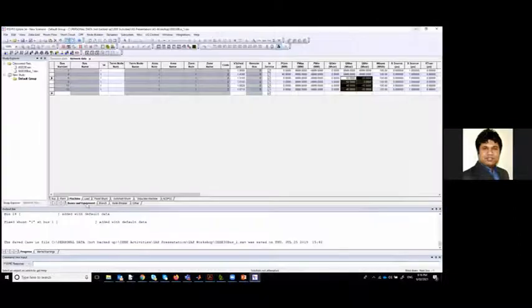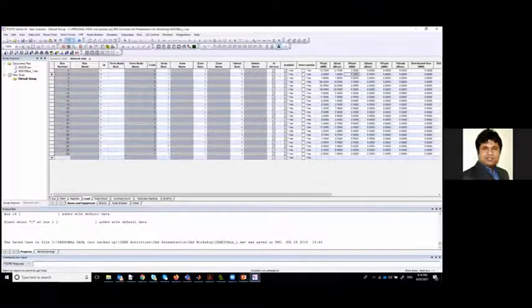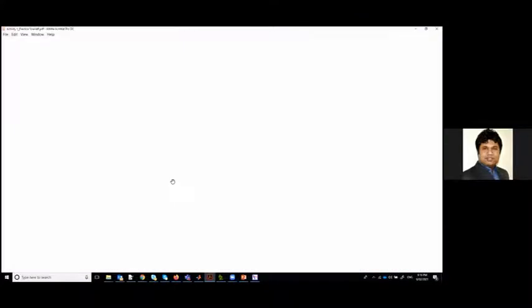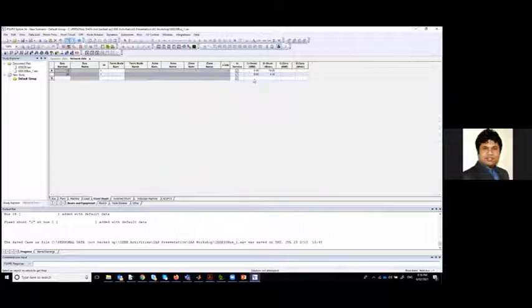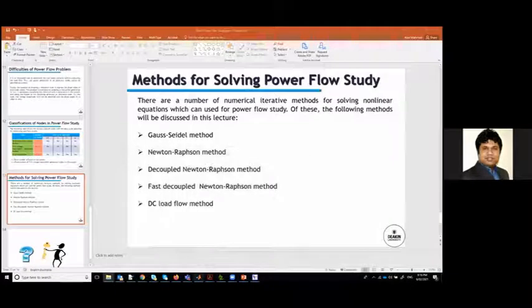Load information is given as well, okay? If you go here, all this PL and QL is given, so I put in all the load information. Then I put the shunt: 19 at bus 10, 24 at bus 24, 4.3. Basically, I multiplied whatever I have got here.